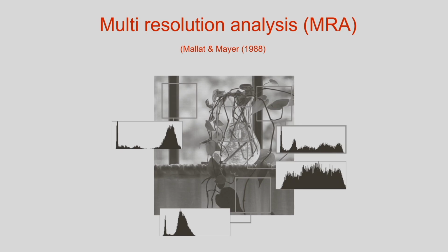That means analyzing the signal at different frequencies with different resolutions. It is also important to analyze a signal both in the time domain and the frequency domain. But the problem is the uncertainty principle, and I have already explained that concept. The point is that at high frequency we have good time resolution and poor frequency resolution. On the other hand, we have good frequency resolution and poor time resolution at low frequencies.